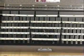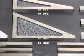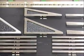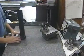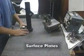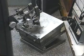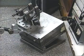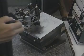Gauge blocks are produced in several grades or degrees of accuracy, and are also produced with angles to furnish simple and accurate measurement of any angle. In addition to gauge blocks, measurement areas typically utilize surface plates, which are flat planes produced from hard, homogeneous granite. Surface plates hold extremely tight tolerances and are used as a reference surface from which dimensions or other measurements are taken.